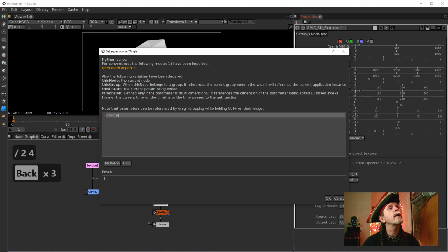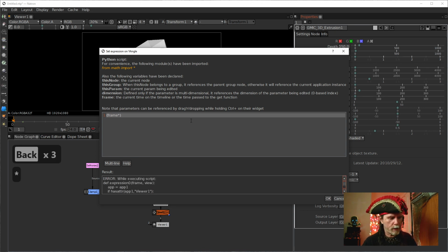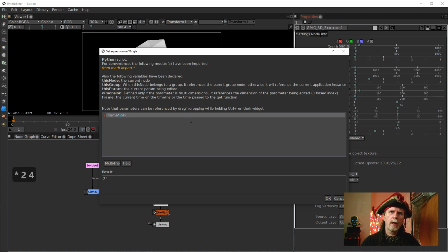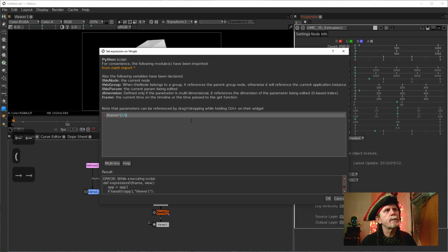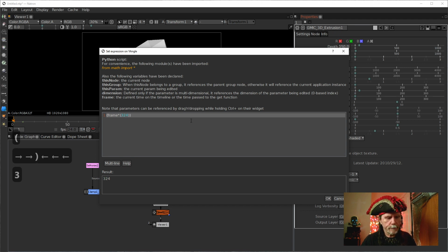Let me think about it. No, frame times 24. Excuse me, times 24. All right, so every frame we're going to rotate this by 24. Let me just think about that. Is that correct? No, what we need to do is make it frame times 360 divided by 24. There we go.